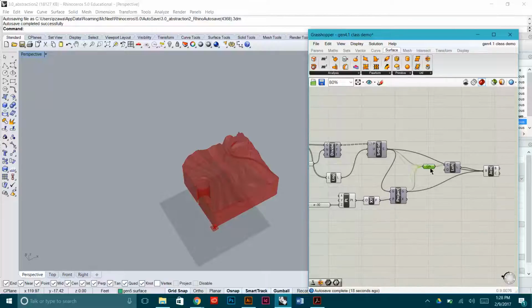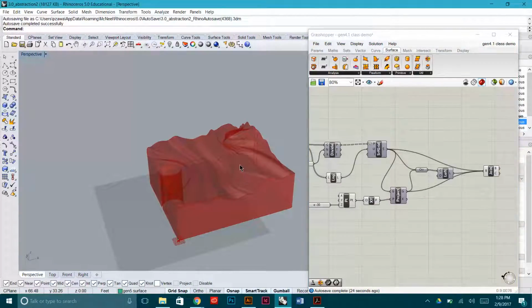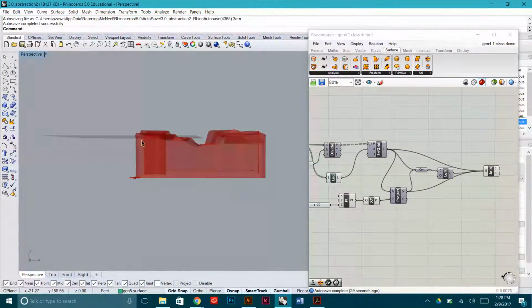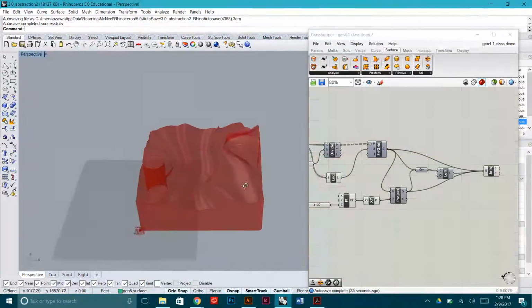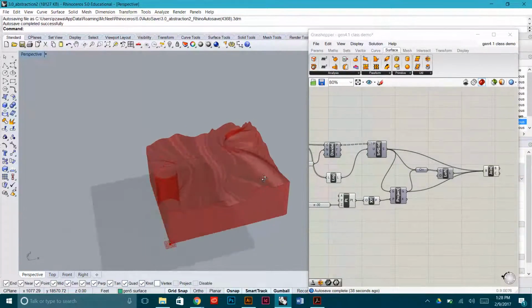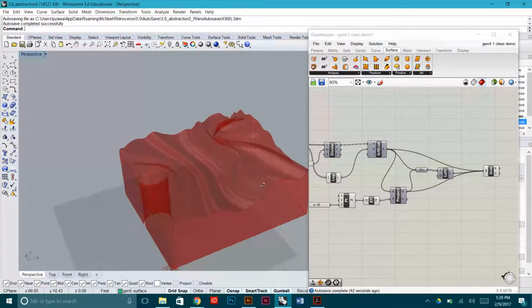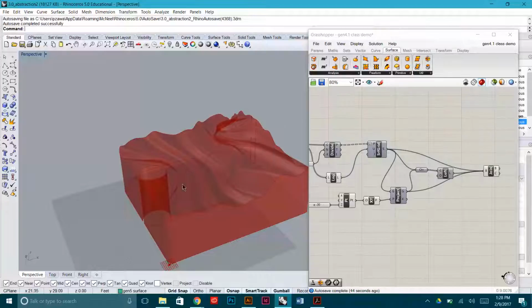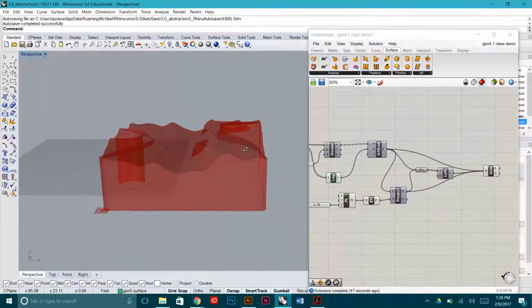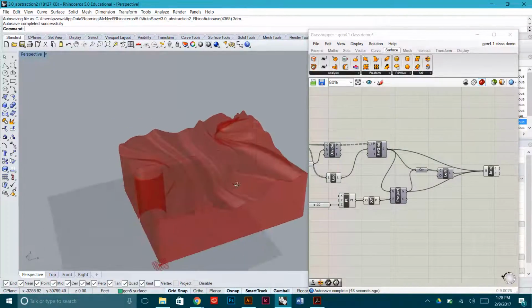So let's create our contours for it now. When you're doing the actual contours for this, you don't have to do it for your entire volume. You might when you get into the fabrication phase where you need to start stacking this, but for graphic purposes, you're just going to want to contour your surface itself, not the rest of that.